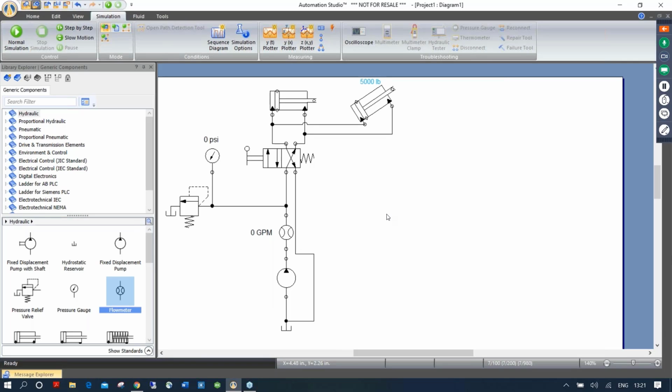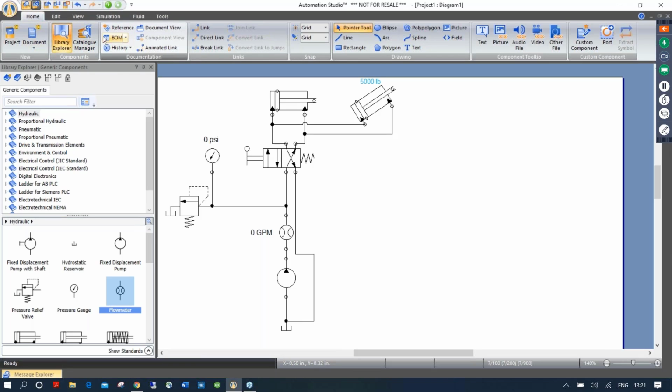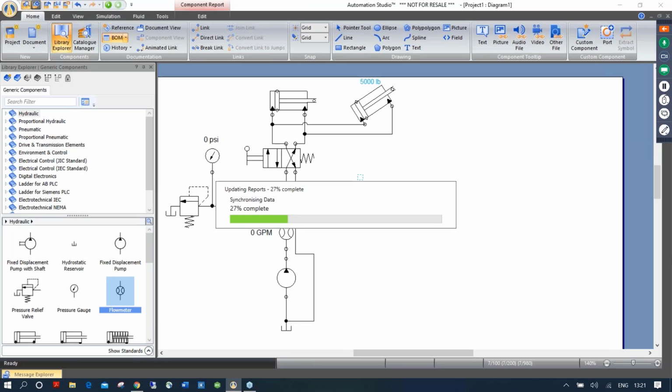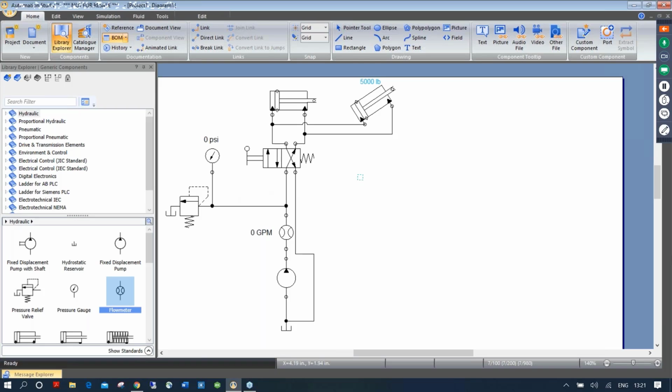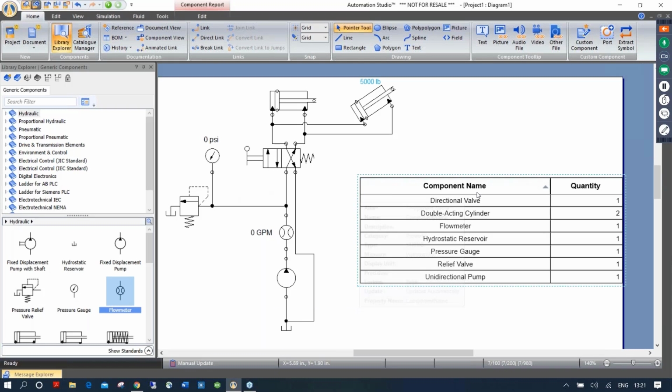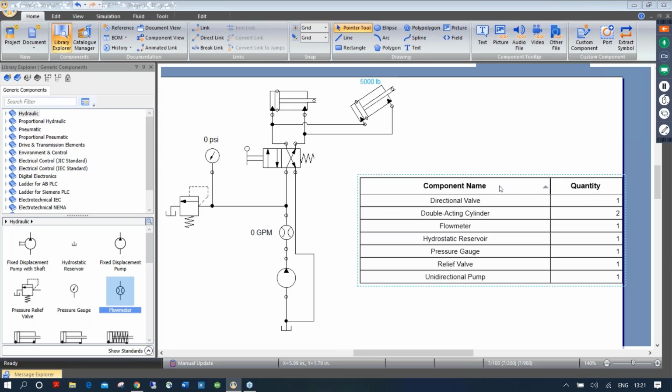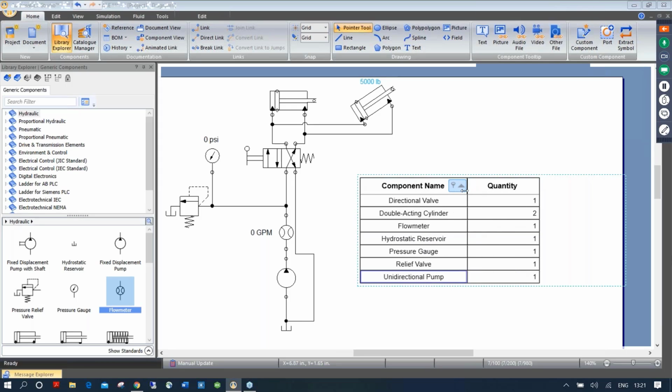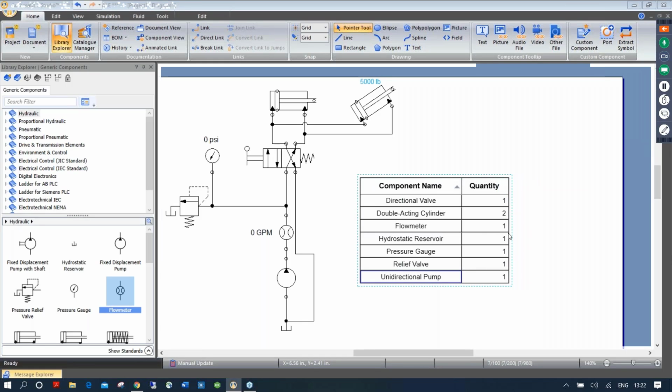It is a professional CAD drawing software. So for example, I can also insert a bill of material, a BOM. So I can just do a little square here, and it's compiling now the information of what's on my drawing, and it's going to display it on a bill of material that I can actually modify at will. If I unlock it, I can actually shrink it like this. I can double click on it, go change the field that I'm displaying. I can add fields. It's really customizable the way you want.